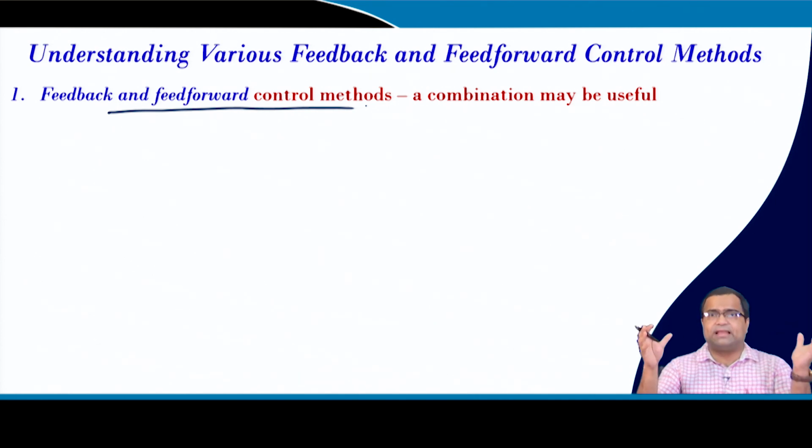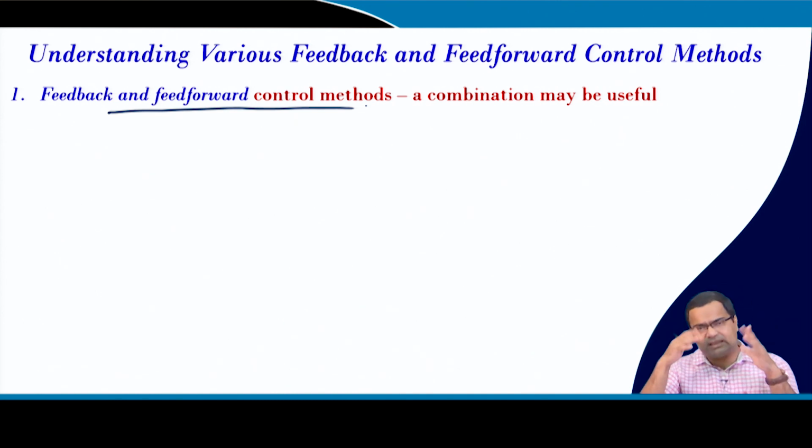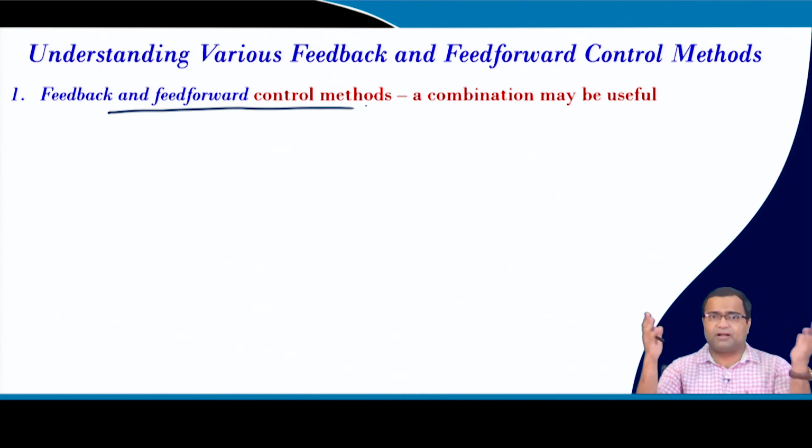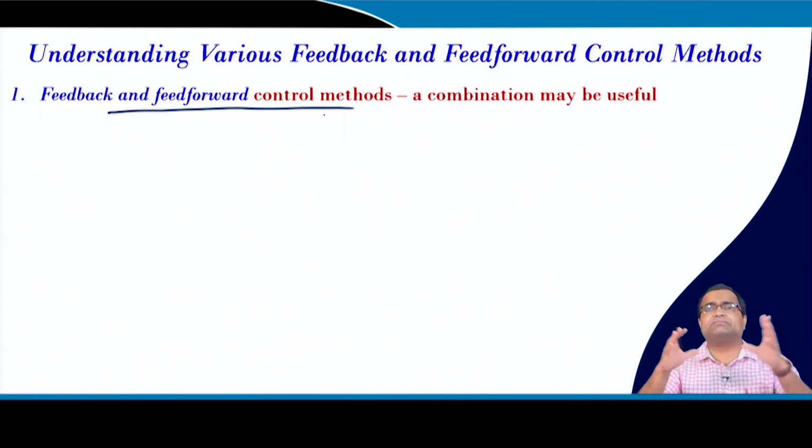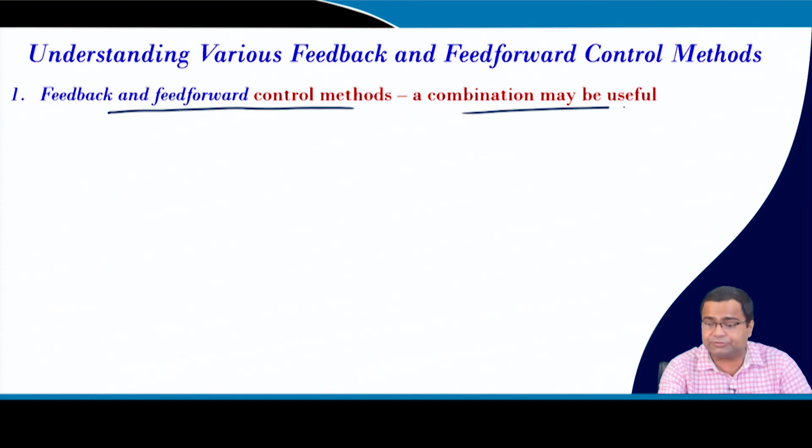And in the subsequent lecture on tuning we discussed this combination, because if you recall, voltage mode control suffers from poor line regulation, and current mode control suffers from poor load regulation. So, for voltage mode control, we need to consider input voltage feed forward. For current mode control, we need to consider load current feed forward. By this feed forward method, we can make their performance very high and fast, almost insensitive to disturbance, with an excellent disturbance rejection property, and this can be very useful.